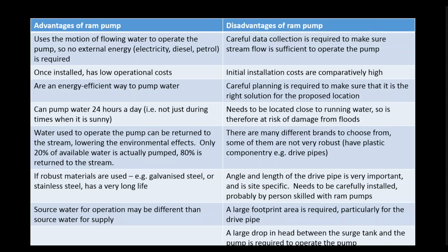So I just wanted to go through a few advantages and disadvantages of a ram pump. The advantages include that it uses the motion of flowing water to operate the pump, so you don't have to pay for petrol or diesel or electricity to run the pump. And because the water is constantly flowing, it's not just during daytimes or when it's sunny, it can actually pump for 24 hours. And once installed, the operational costs are pretty low.